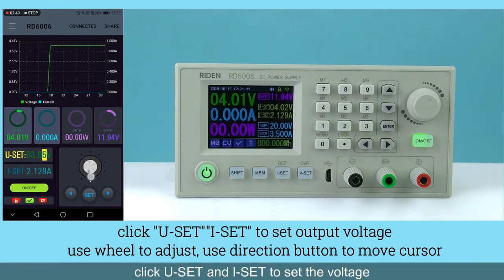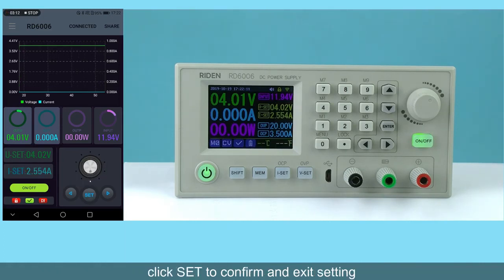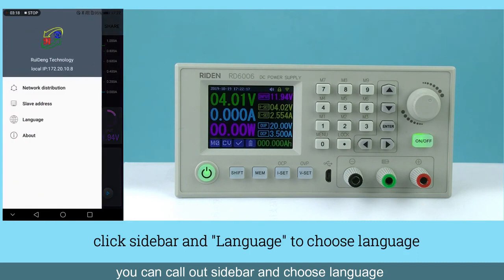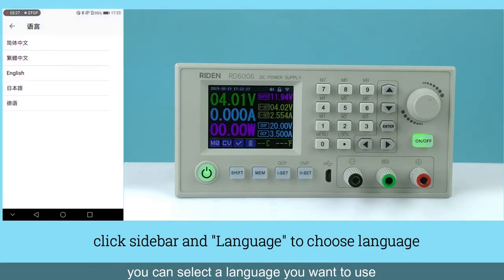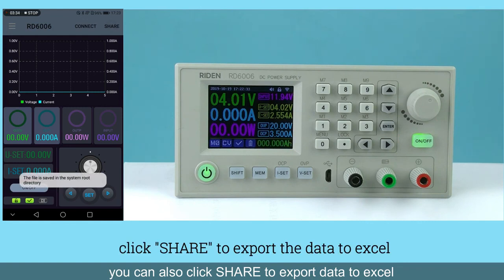Click U-set and I-set to set the voltage. You can use the wheel to adjust and use the direction key to move the cursor. Click Set to confirm and exit setting. You can call out set bar to choose language. You can select the language you need to use. You can also click Share to export data to Excel.